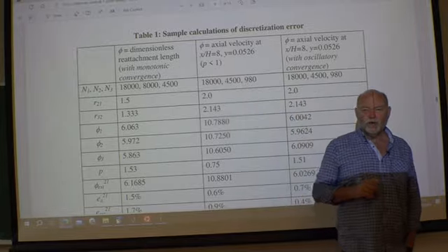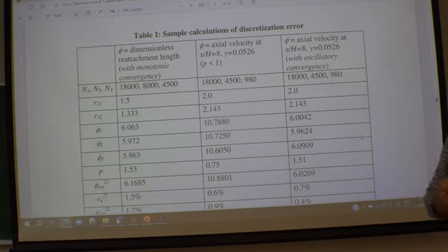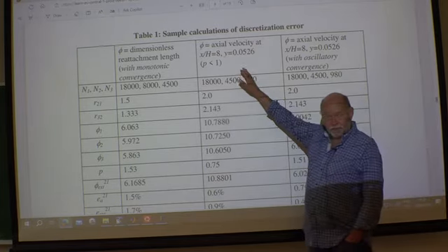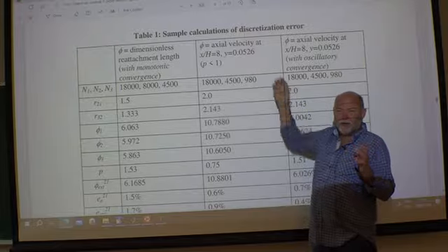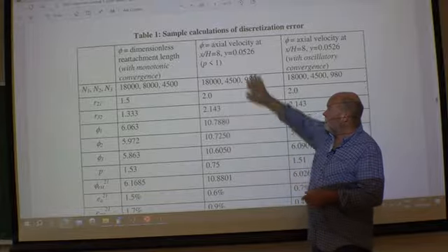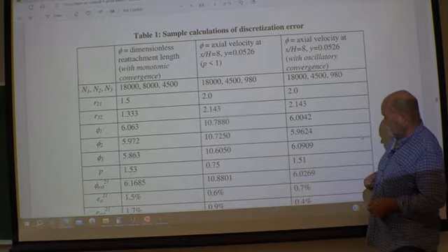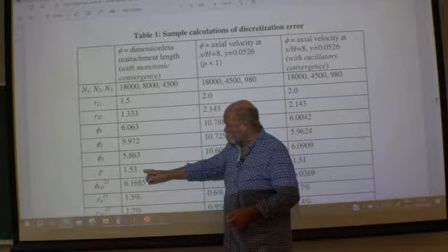Apparent order is smaller than 1. Come on, that is not good. Bad monitor. Doesn't have to be anything wrong with your simulations. It's just a poor choice of finding a monitor that is sensitive to the physics in the problem. So, out the window. This one, better. Let's just focus on this one.